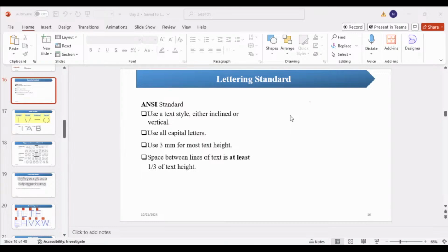Pin එකක්, අල්පෙනෙත්තක් වගේ දෙයක් පාවිච්චි කළොත් ඒකෙන් paper එක හිල් වෙනවා. Therefore, that is why normally we use paper clips or adhesive tapes. Normally those adhesive tapes won't damage the paper, but they will prevent the moving of the drawing paper, right? Tape එක කොලේ ගැහුවට කොලේ ඉරෙන්නේ නැහැ ගලවද්දි. ඒකෙන් අපිට ඕනේ කාර්ය සිද්ධ වෙනවා. So normally we prefer adhesive tapes or paper clips rather than pins.